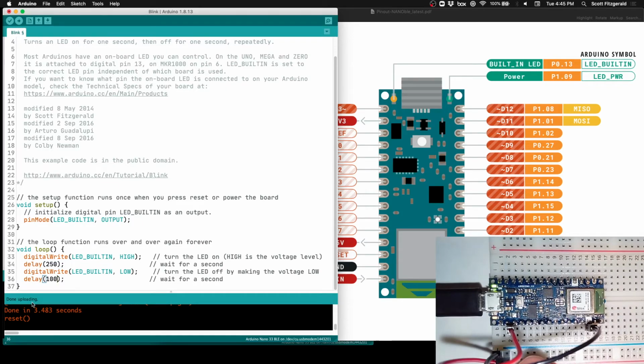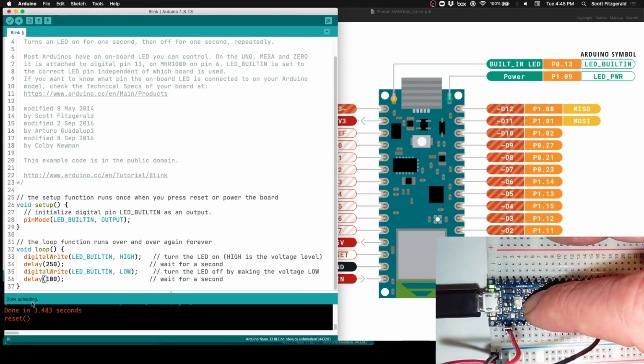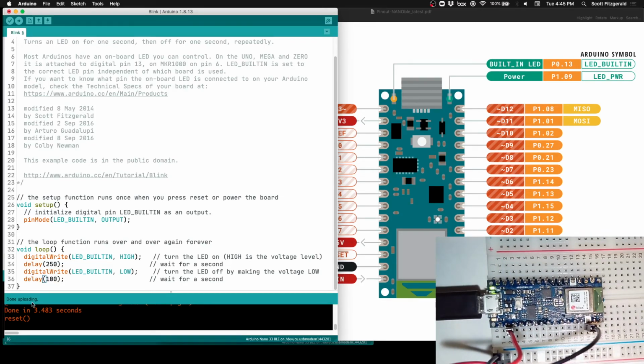And you'll notice that the board right now is not blinking, and instead this LED is like breathing, it's pulsing, right? So sometimes that happens when you upload a new program after like the second or third time you've uploaded the code to your microcontroller after you've plugged it in. So if you ever see that after you've uploaded it and you don't think that your new code is running on it, all you need to do is press the reset button, this thing right in the center. So I'm going to click that real quick, and now I can see the light is blinking really fast, right? So by pressing that reset button, what it does is it forces it to go through the setup and then start the loop of whatever was most recently programmed on there.